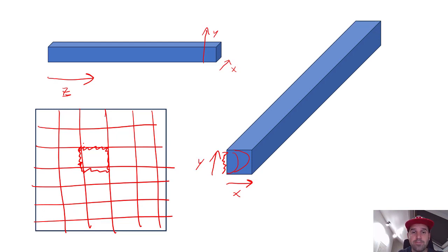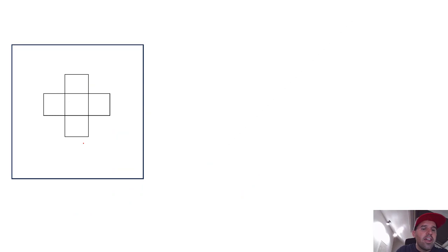and we'll use this finite difference approximation method to solve that. All right, so if we looked at our system and we looked at one of these nodes or control volumes that I just mentioned, we're going to do an energy balance here. So I'm going to call this the i, jth node, where i tells us which node we're in as we're going from left to right in the x-coordinate, and then j tells us which node we're in as we're going from bottom to top in the y-coordinate.